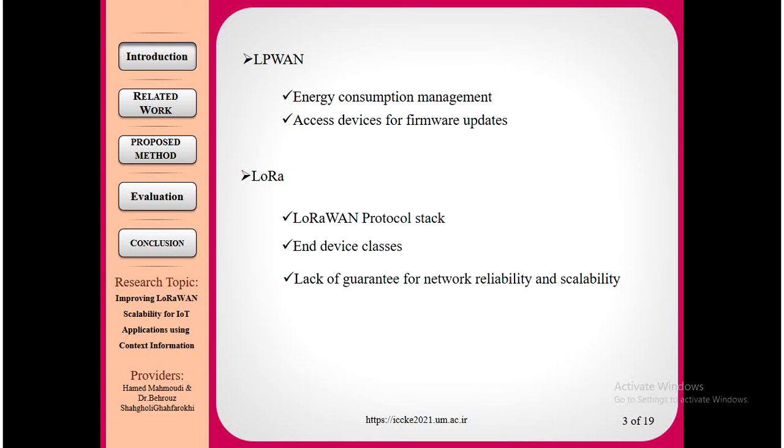There are some circumstances where using LPWANs is not optional, and we have to use them, especially when energy consumption of devices is important or when accessing the devices is difficult. For example, when the device is installed in woods where there are wild animals and everything, it's better to use LPWANs. Also when we need to update the device firmware or we need not to replace the battery of devices for a long time. LoRa is one of the LPWAN technologies.